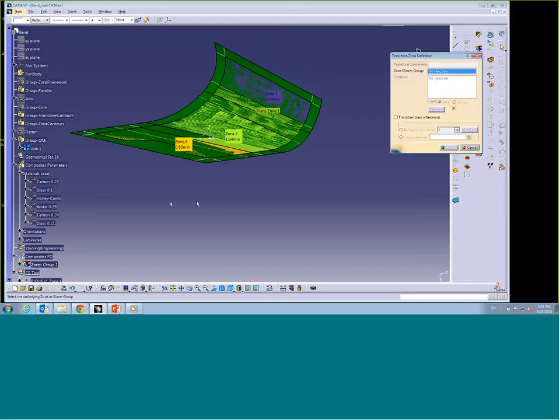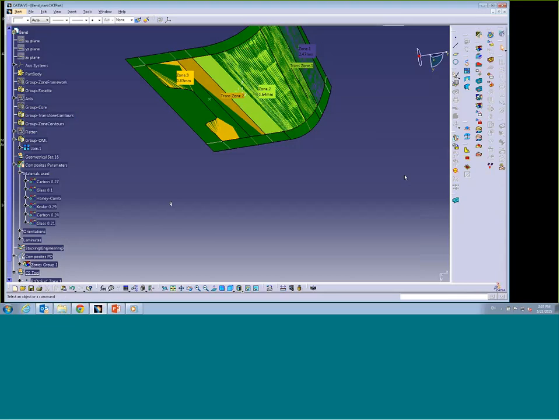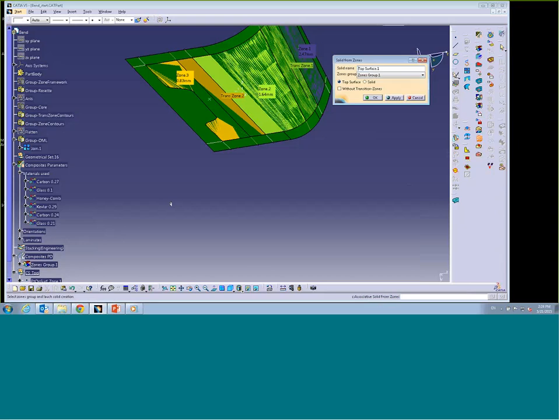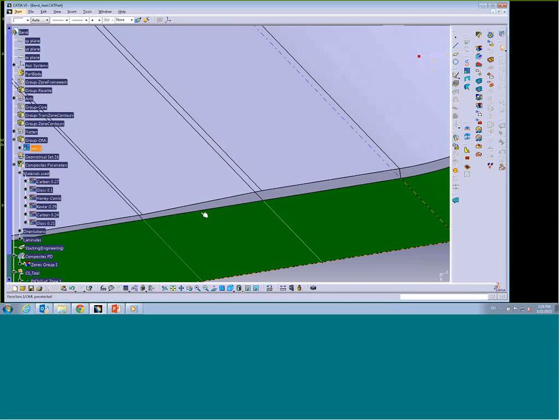And I'm going to create another one. I want to ramp from the middle zone to the yellow one over this area, this width. So the underlying zone is zone 3. And the contour is going to go from here to here. Green check mark. All is good. So now if I try to create a solid, which I did before, that's a drop-off. That's associative solid from zones. Okay, now you see it shows nice ramps right there.